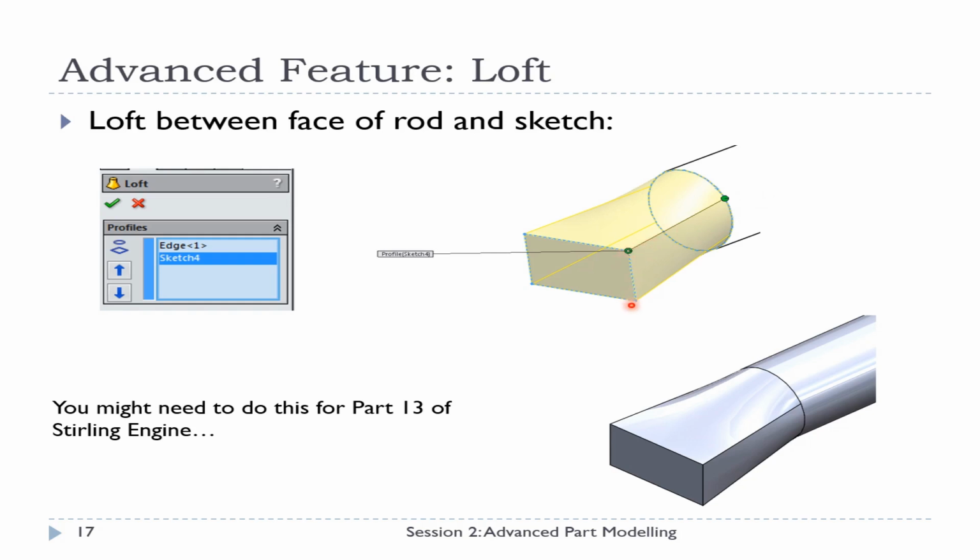So when you are using loft, you can effectively drag and drop these control points at anywhere along the relevant sketch. So let's have a look at this example. You can simply drag and drop this point to this bottom corner. So in that case, it's going to be blending this bottom corner with that control point here on the circular profile.